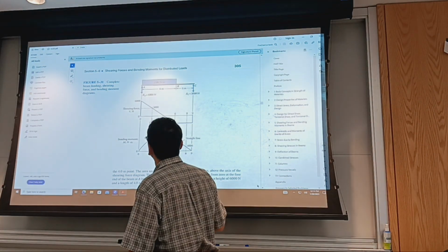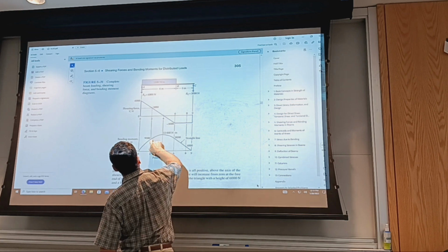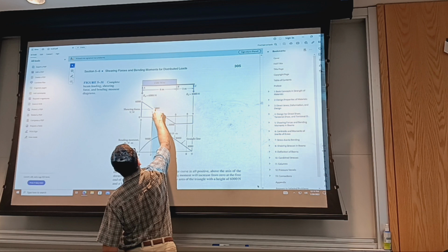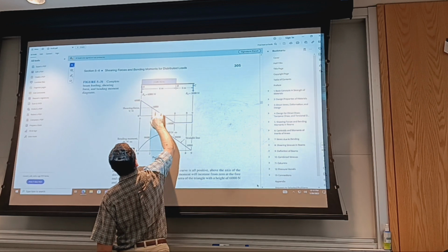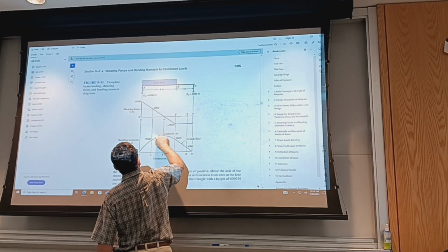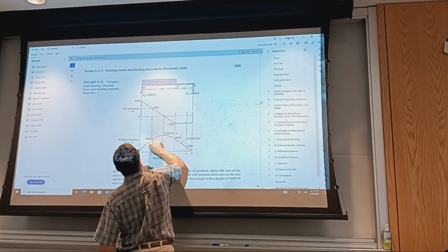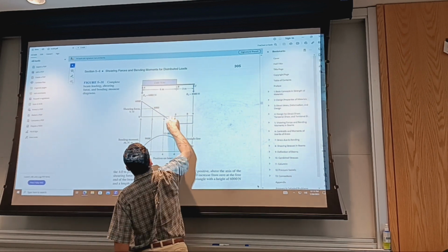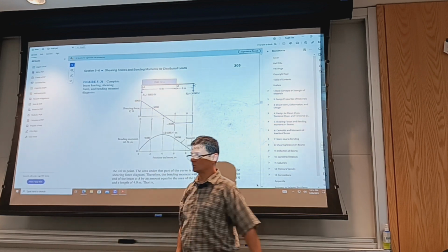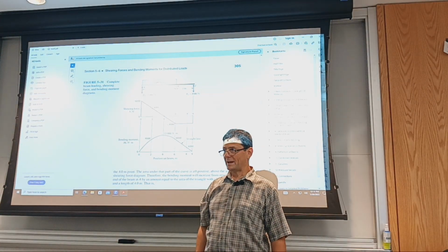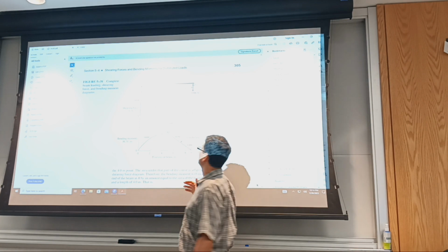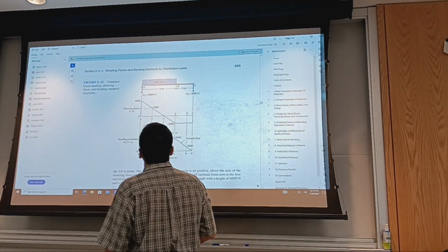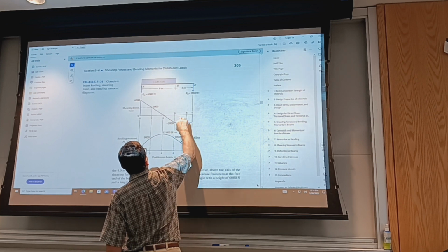All right, but the same applies. If I want to know the slope around this point of this line, I read it here. So if this is 3,000, the slope around this point on the moment diagram, I read it here. When the shear diagram goes to zero, the moment goes to a maximum or a minimum. It could be global or local. And then you see here the transition.